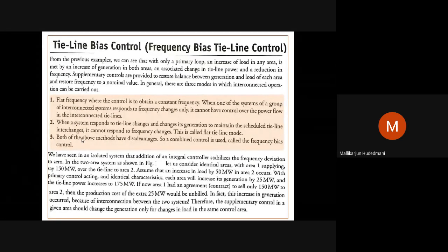In the second concept, only a few or all of the generators are going to respond only for a flat delivery, and nobody will concentrate on frequency here. But that is an adverse phenomenon. Both should happen. If that is the decision, then who should respond for frequency control and who should respond for the megawatt balance? This becomes an issue, because we don't know that all the generators will be in practice all the time.